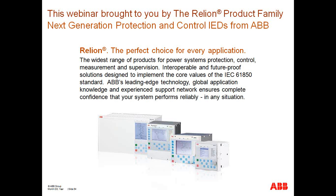The way this was thought of is really similar to a line differential relay applied in a SONET network, where you can have asynchronous, unsymmetrical delays on your channels. As part of the Ethernet packet that contains the sampled measured value data stream, there are flagged bits for synchronization. And if the merging unit loses its source of synchronization, it will set this bit, and in turn, the particular devices that are associated with that data stream will know that the synchronization has been lost.